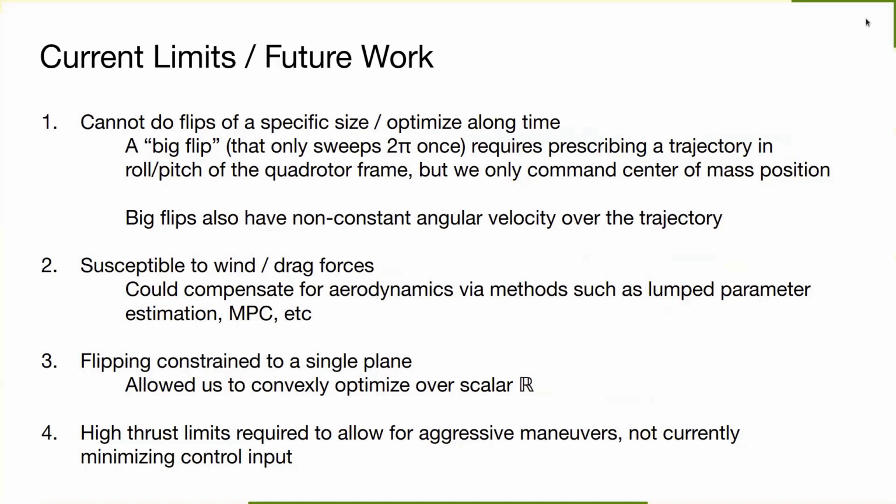Flipping is also currently constrained to a single plane to allow us to optimize over a scalar rather than the space of 3D rotations. Finally, for flips, we are currently not minimizing control input and allowed for rather high thrust limits to achieve the aggressive maneuvers.